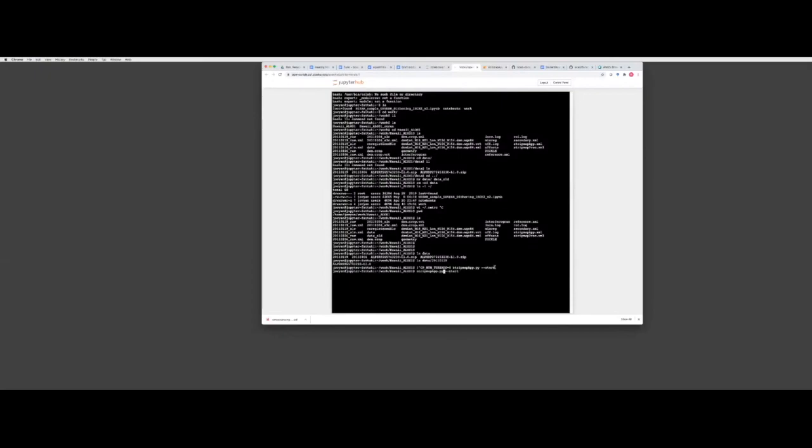In your Hawaii ALOS-1, you can just do stripmapApp.py stripmapApp.xml --start=startup --end=endup. So this should go through everything. Or if you want to start from topo, you can just say from topo. But before that, you have to have OMP_NUM_THREADS set, as Piyush suggested, or something like that.